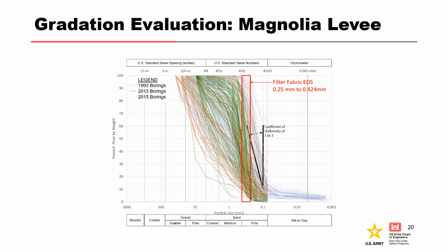However, even that parsed data may be misleading if none of the samples are from the critical locations or weak link in the foundation. This mass gradation plot was subsequently pared down to the depths of interest and below the roof-forming material. The equivalent opening size, or EOS, shown on this plot is the range of openings in a filter fabric placed beneath riprap at a downstream seepage exit.